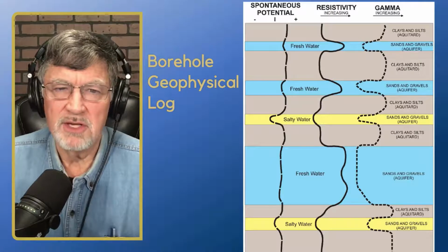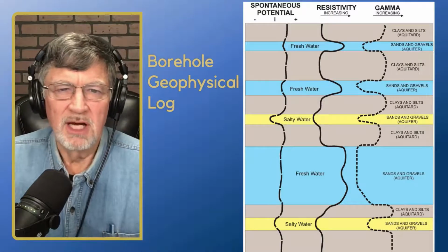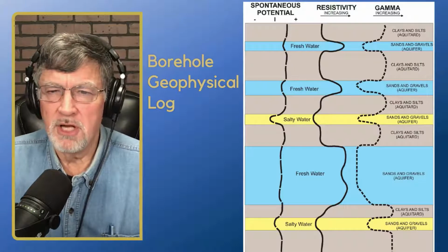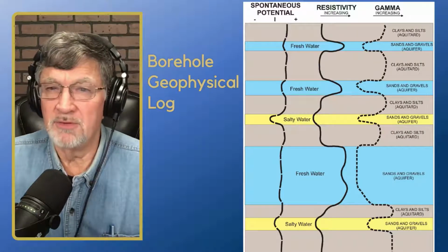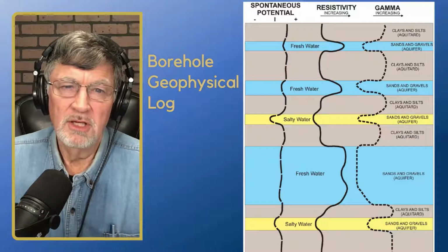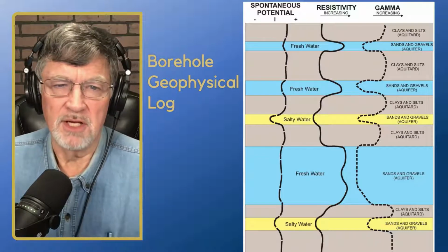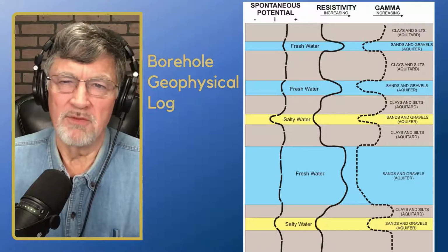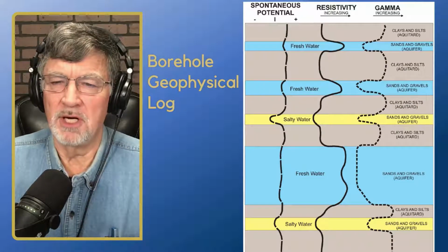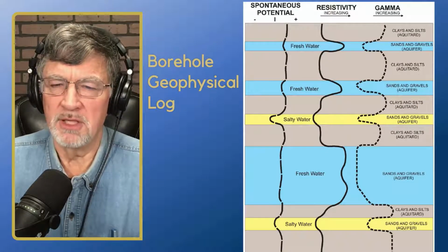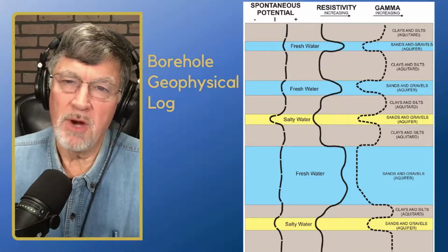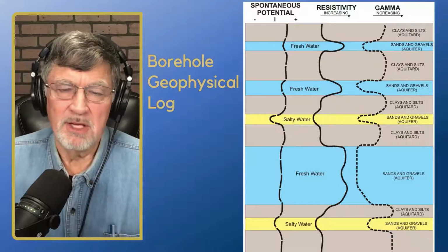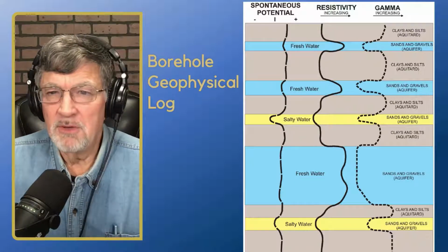So that ends up being a decision based on the geologic log, the geophysical log, and probably some knowledge of the area itself. One of the things we do during well siting studies is we look at other well logs and see what problems they've run into, and see if we have any heads up on water quality issues. But in this case, we may want to actually go in and test all 5 of these zones and run some mass balance and determine if it might be worthwhile.